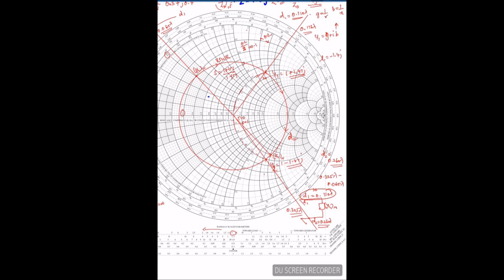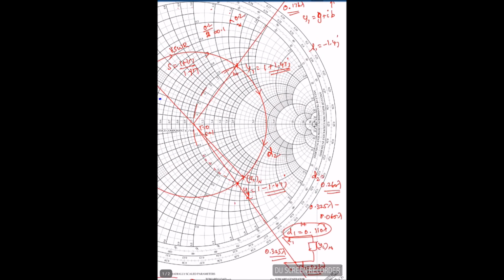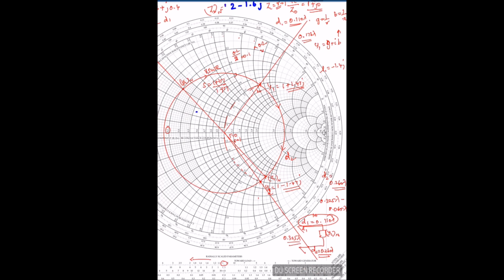Now for completeness of the problem, we will find two solutions for this problem. Once I know the distance, half of my job is done. The other thing is I want to cancel out the reactance part of these two admittances y1 and y2. From zL n we put 180 degrees and get yL n, that is the normalized admittance.